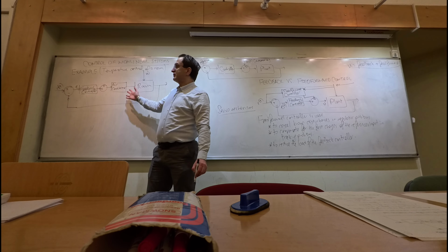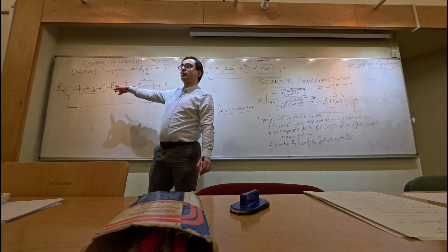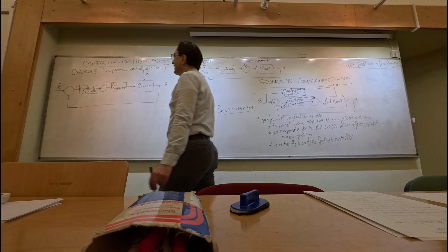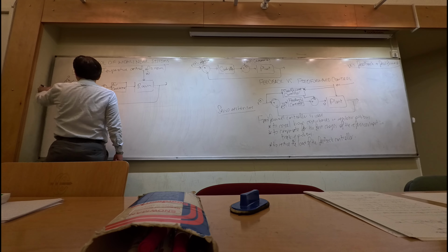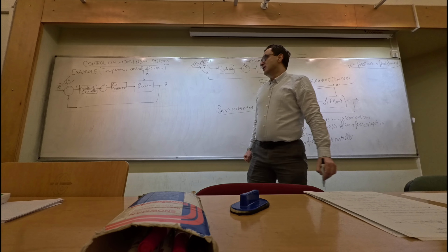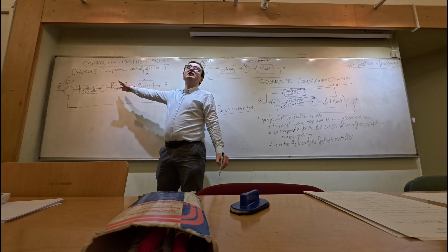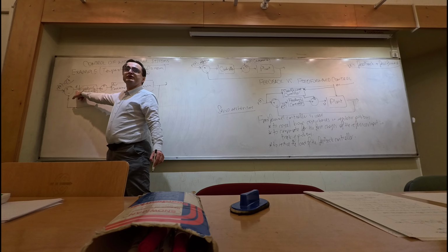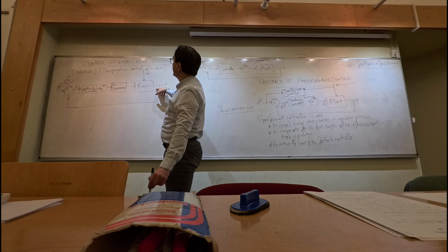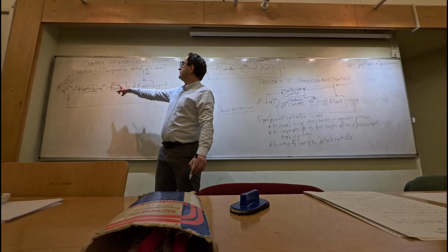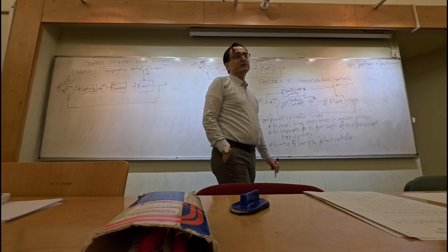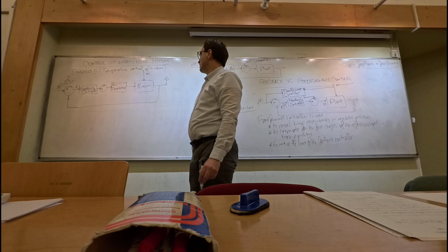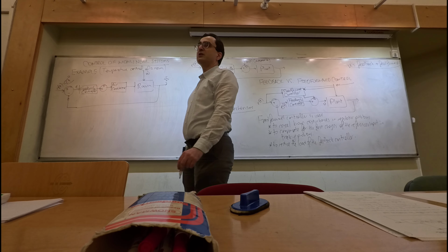In general, when this feedback loop is working, what has to happen for the feedback controller to work is that there should appear some error signal in the system. Suppose that this reference is actually constant. Let us say that it is 27 degrees. So for the feedback controller to work, whether to make the room warmer or cooler, there has to appear some error signal in this part. So here, the room temperature should actually change before a feedback controller can take action. For example, if this is 25 degrees, then we're going to start to heat the room. Or if it is larger than 27 degrees, then we are going to start cooling the room.